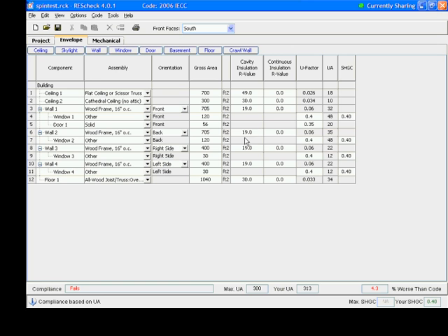The walls are R19, and in this climate zone, that's what the insulation value calls for. So we're meeting the walls nicely. So let's go down past these walls and let's go to the floor. The floor is meeting it as well. I'm not really upgrading anything anywhere. So why am I not meeting code? If I am meeting the minimums, why am I not meeting code?